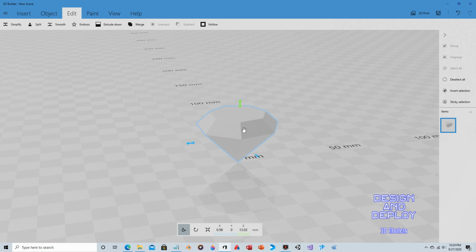I'm not going to do it in 3D Builder because there seems to be an issue where when you apply a material or you apply a color, if it's not the default color, it gets lost when you export it. I suspect it's a defect. When you export using the OBJ format, there's actually 2 files. There's the OBJ file and there's an MTL, a material file. So even though both files are included, it doesn't seem to save the changes. So I think that's a defect, and I don't think it's ever going to be resolved because I have not seen any changes to this application in a very long time.